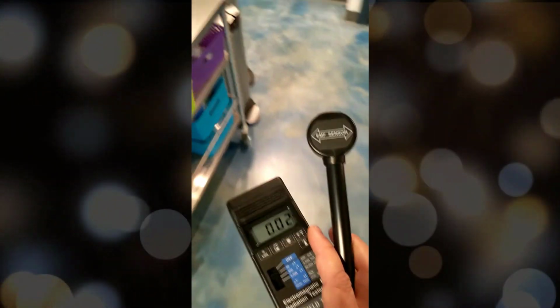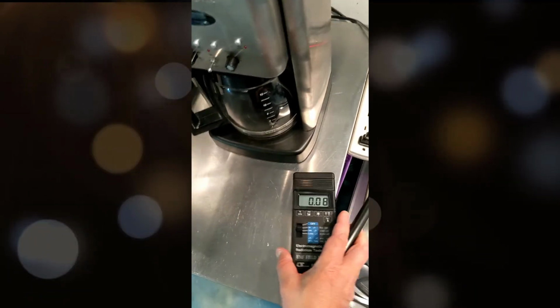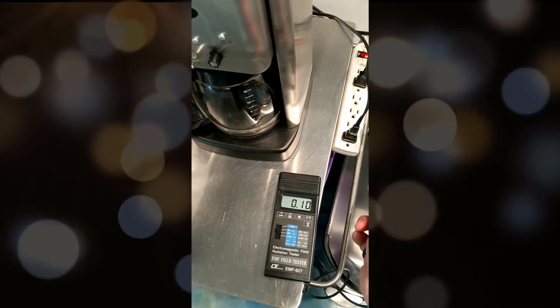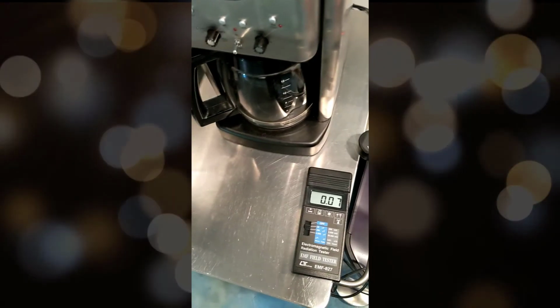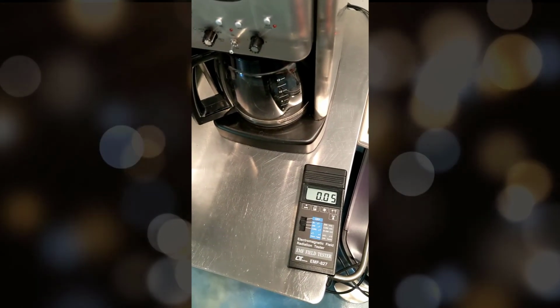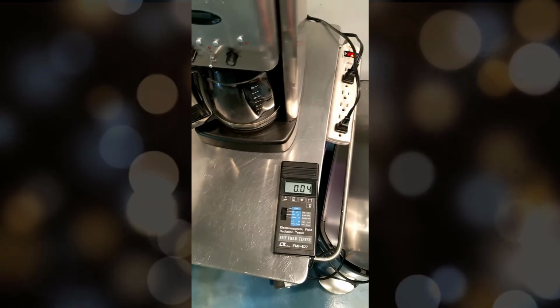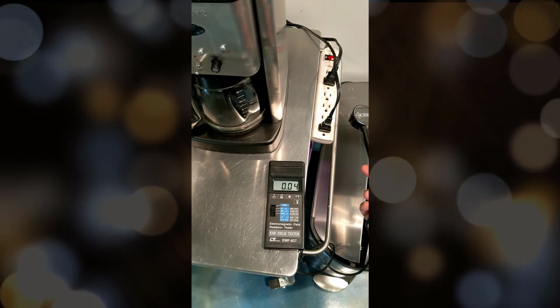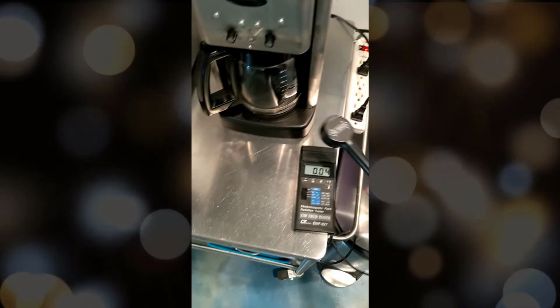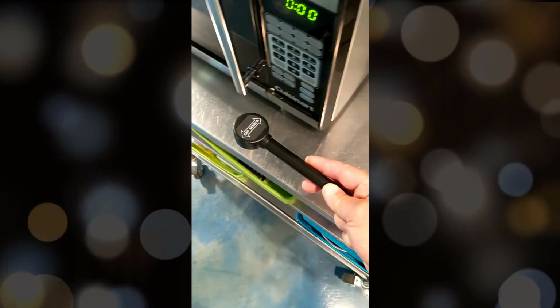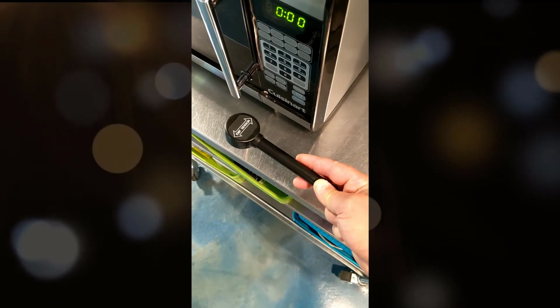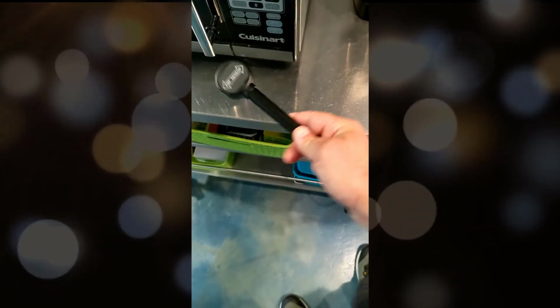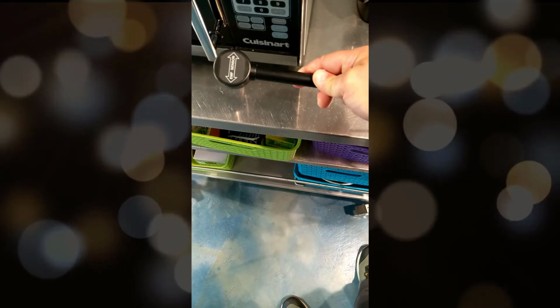Another thing you might find is something that's just powered with a 2-prong plug. So you can see close to this cord I'm getting a little bit, but hardly anything to be concerned with. Our threshold would be about 4 milligauss, so a reading of 0.4. So with the microwave off, I'm getting a reading of about 1 directly in front of it.